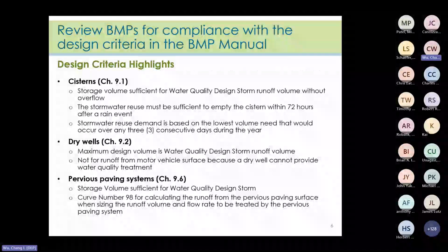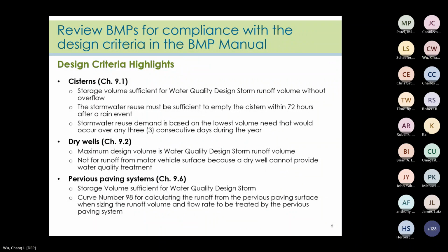If clean roof runoff is intermingled with the runoff from the motor vehicle service, then it cannot be directed to a dry well. Although a dry well cannot be used to treat runoff from motor vehicle service, it can treat clean roof runoff, and you can use that to reduce the runoff for the quantity design.